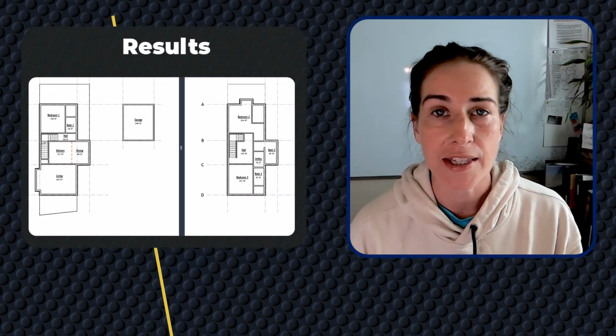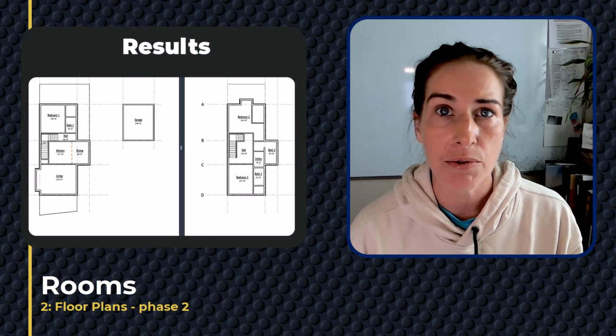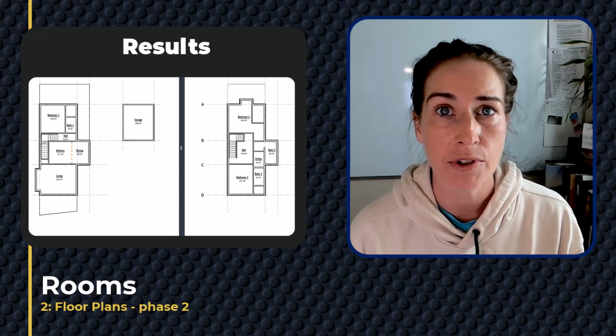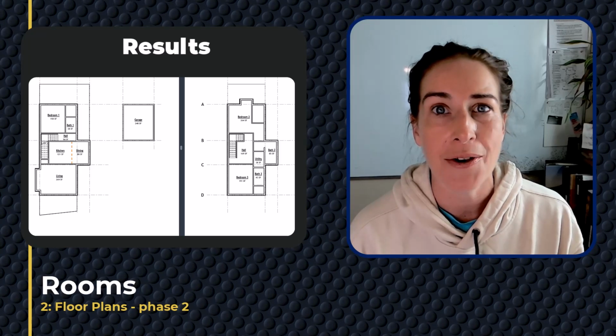As a reminder, in this video we added rooms. We added a room separation line and changed a few walls to non-room bounding. We also modified our room tag. I hope this helps.